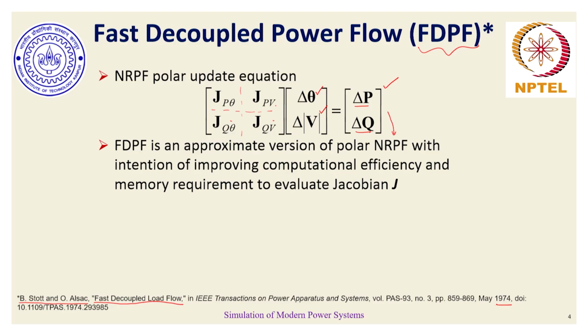The main challenge or problem that they tried to solve was that in every iteration of Newton-Raphson power flow, this Jacobian matrix, which would be a large square matrix, often a sparse matrix, but a large matrix, for a large power network, would require continuous evaluation of this Jacobian, and also its own factorization so that the corresponding state variable changes can be known, provided these mismatches are also being evaluated.